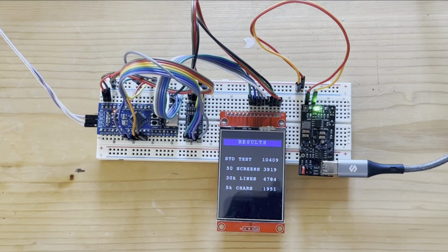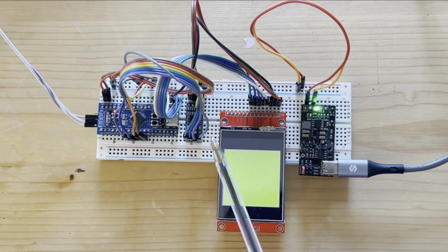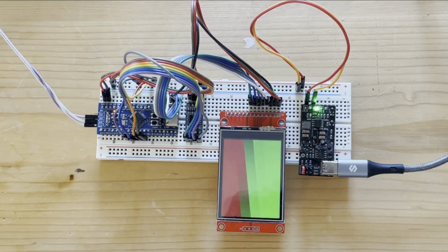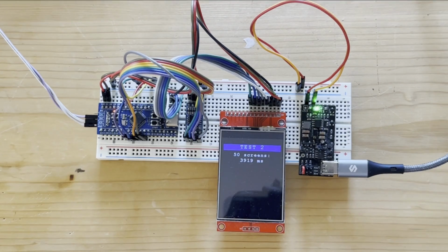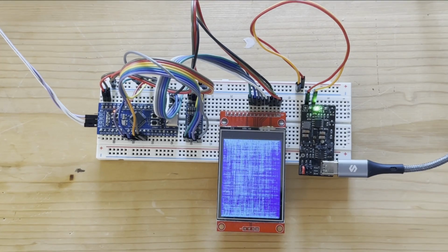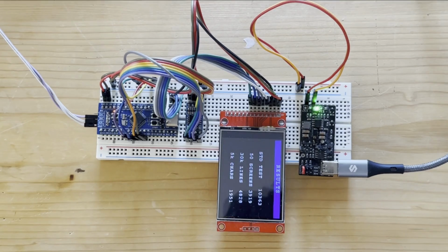Here you see I ran the display test you already know. Other than the display, you see I added a W25Q64 flash via SPI. Display is on SPI 1, flash on SPI 2. Again I'm using it with my handling library, and again I suppose you have previously seen the related videos. Below in the video description you will find the link to my flash handling library also. So the project is set and working, even if right now the flash memory is just connected and set, not used yet.